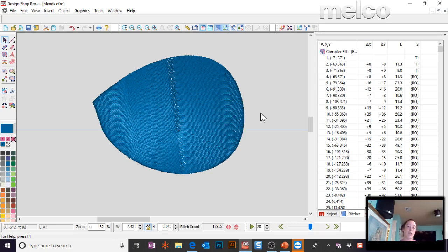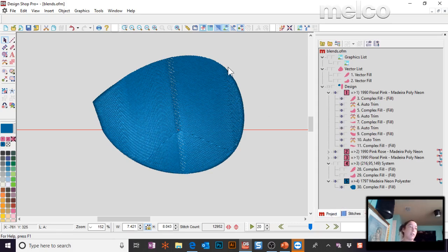I can try to get back to you, see if there's a better way to avoid it, but what I've always noticed is whenever you're doing a conversion from an expanded stitch type, whether it's your DSTs or your EXPs, it really doesn't matter which, it always ends up where you have points, and often too many within the wireframe, that are just not what you want. So there's always some cleanup. I've also noticed densities change. It'll make a guess at a density which is not accurate. So anytime you do those conversions, I always find there's cleanup work to do.